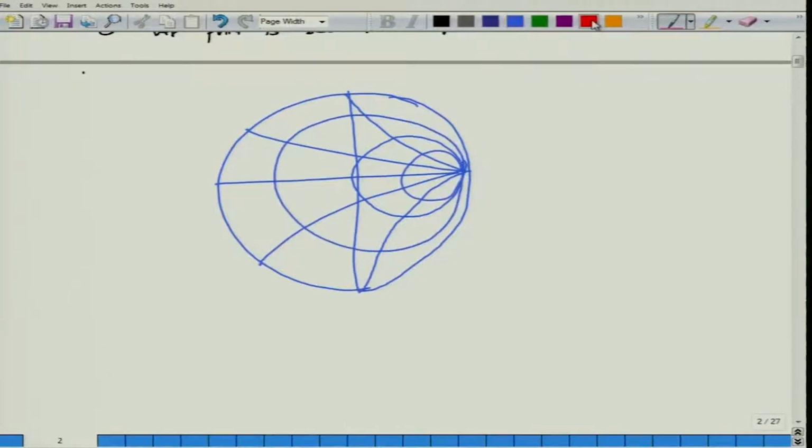The first step is to again locate r equal to 1 and j equal to 1. In this case, this happens to be the point here, which is the point A. This is the load point. A is the normalized load value with center O and OA as the radius. I draw the constant SWR circle. So, I have completed step A, I have completed step B.